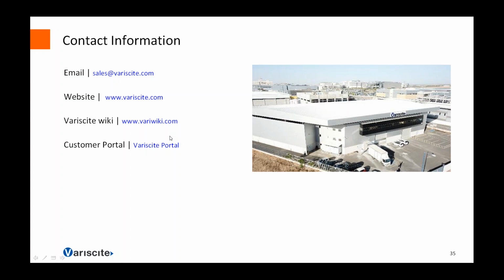If you look at our BSPs, you will see that when building the FreeRTOS part, we point you to a specific ARM compiler available online from the ARM website. We just rely on ARM for bare metal compilation.